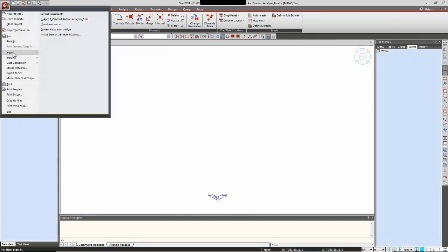And lastly, we have got the importing tool, wherein the Revit or Tekla files can be converted into MIDAS Gen text file and can be imported over here. Then 2D, 3D DXF files, AutoCAD DXF files can be imported. SAP as well as STAAD files can be imported directly in MIDAS Gen. In this webinar, I will be using AutoCAD DXF file, a 3D DXF file, to start with the model.